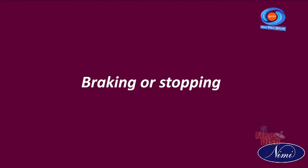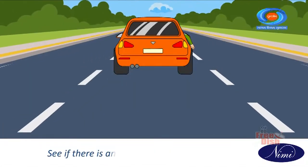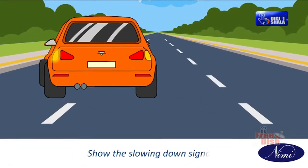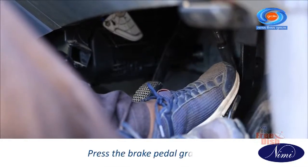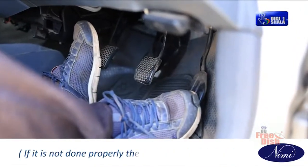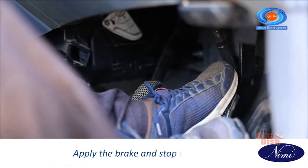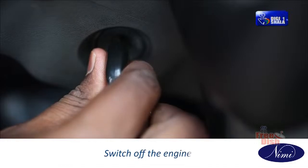Task 3. Braking or stopping. Check for any vehicle in the rear view mirror. See if there is any vehicle behind your vehicle. Show the slowing down signal and slow down the vehicle. Press the brake pedal gradually, and just a little before stopping the car, declutch fully. If it is not done properly, the engine will stop running. Apply the brake and stop the vehicle. Put the gear in neutral, switch off the engine.